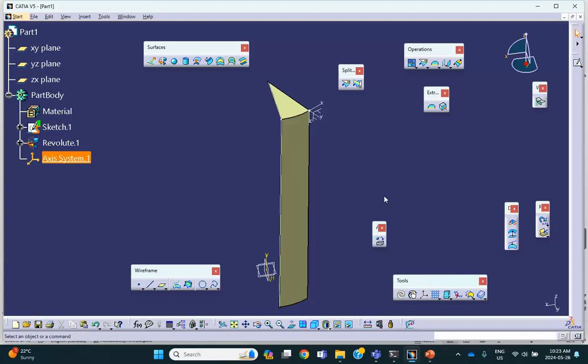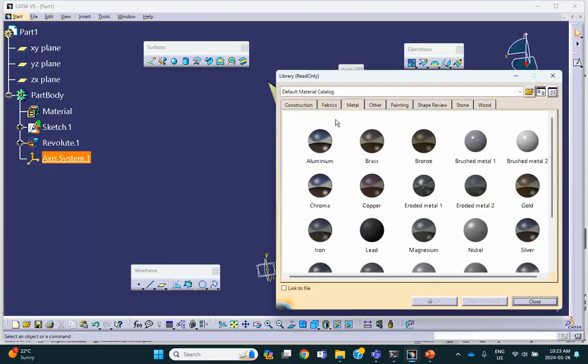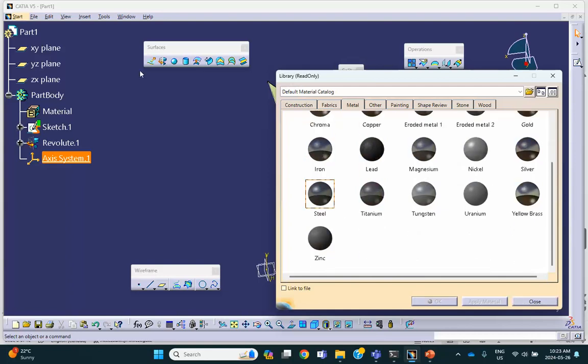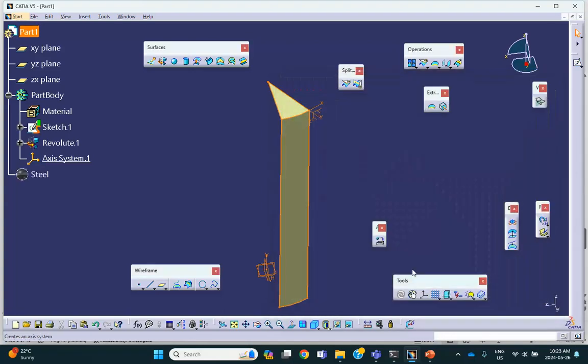So let's apply material to this thing. I think we made it out of steel. Just remember that these stresses, PR over T and PR over 2T, do not depend on whether it's aluminum or steel. The stresses don't matter, but the strains do. So we're going to make it out of steel on that part. Good. And I don't have to join it because of the way I did it, inverted L and revolved it, it is automatically going to be a single surface when I try to mesh it, or when I try to put the thickness on it. Now, if you want, you can join it, but it's not going to do you any harm or any good.